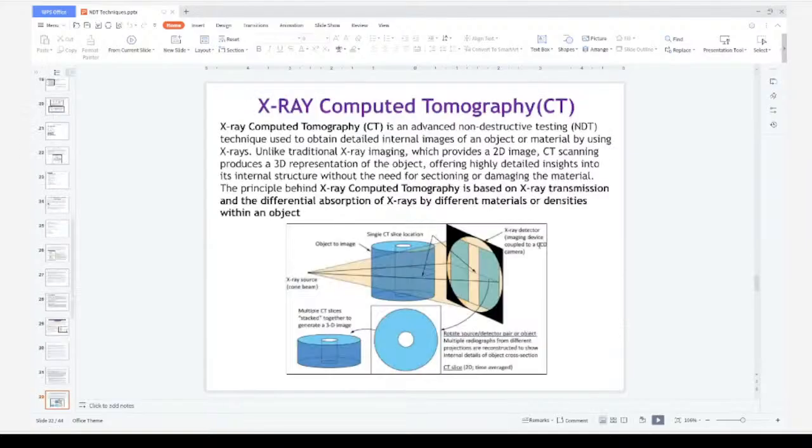Yeah, X-ray CT is the one I was telling you, but it is nothing but an extension of existing X-ray radiography. So the same X-ray source will be there, the part will be there, the screen will be there. Only thing is, everything is automated and a computer algorithm will be there. So you will take 2D scans, and all the scans will be sent to this algorithm, which will stitch them into a 3D image of the part. So here you see, in traditional radiography I will get the 2D regions. Suppose this hole will be seen as a rectangle, but this hole can be seen as a hole in X-ray CT because I will take multiple shots and stitch all the images. That's all.